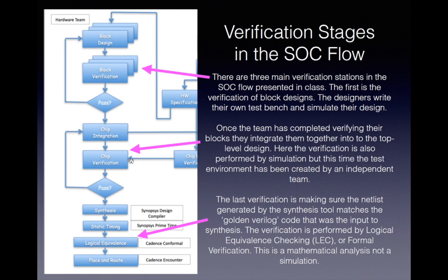Still simulation. Once it works, what we have is the Verilog code that we've integrated together that we've simulated. We now take that Verilog code, which we refer to as the golden Verilog, and we synthesize it. In the Xilinx world, we generate a bit file, or we map it to gates. What we have on the output of that is a representation of our design, this time comprised of library elements from the target technology. The question is, is it the same?